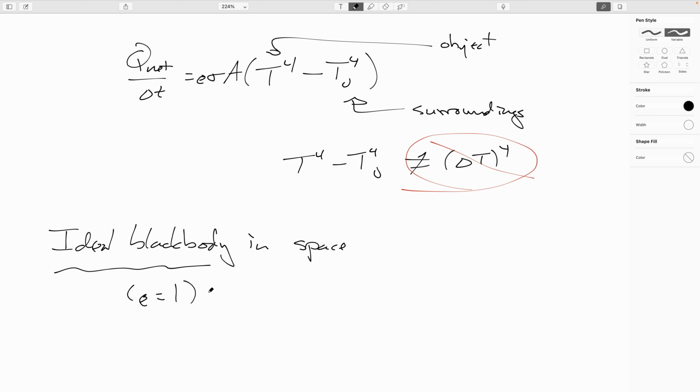When you're out in space, although conduction and convection would be better, they're not available to you. You're not in air anymore and you're not touching anything, so radiation's all you got. And it turns out that gold has an emissivity that's pretty darn close to 1. So if you coat your satellite with a very thin layer of gold, you get this emissivity up to pretty darn close to 1. So this isn't as unrealistic as it sounds. Now the in-space bit is telling us that the temperature of the surroundings is 3 Kelvin, roughly. This is actually due to energy left over from the Big Bang.